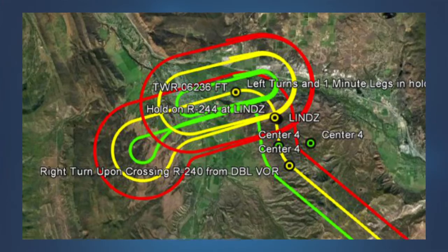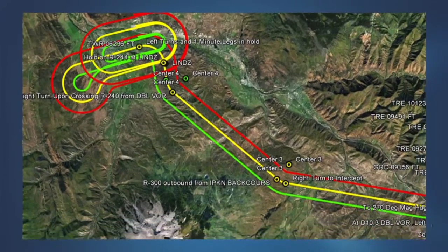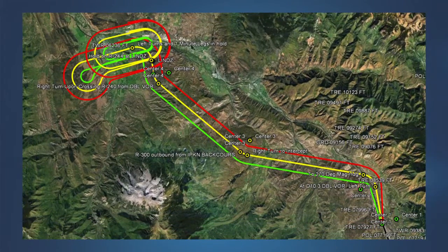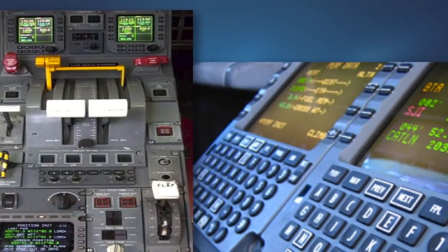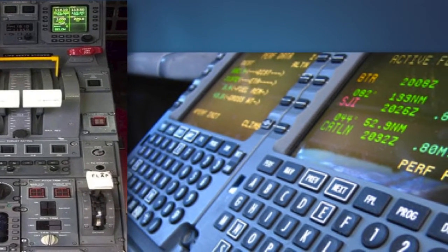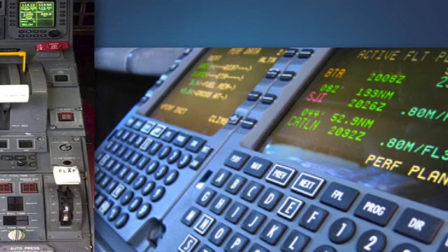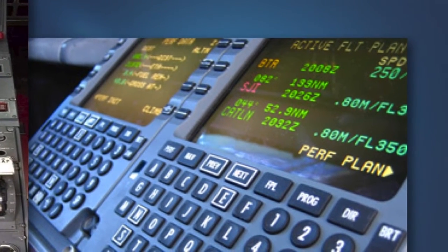V2 speed. Therefore, as we have seen, the area in which the obstacles that must be assessed for net takeoff flight path clearance is smaller than the area used for normal IFR departures. The flight management systems on many business airplanes provide features for computing airplane performance, including climb weight limitations. Pilots should be aware that the results provided by these systems are only as accurate as the obstacle information entered by the pilot. If the pilot enters the climb gradient requirement published on an IFR departure procedure, the results may